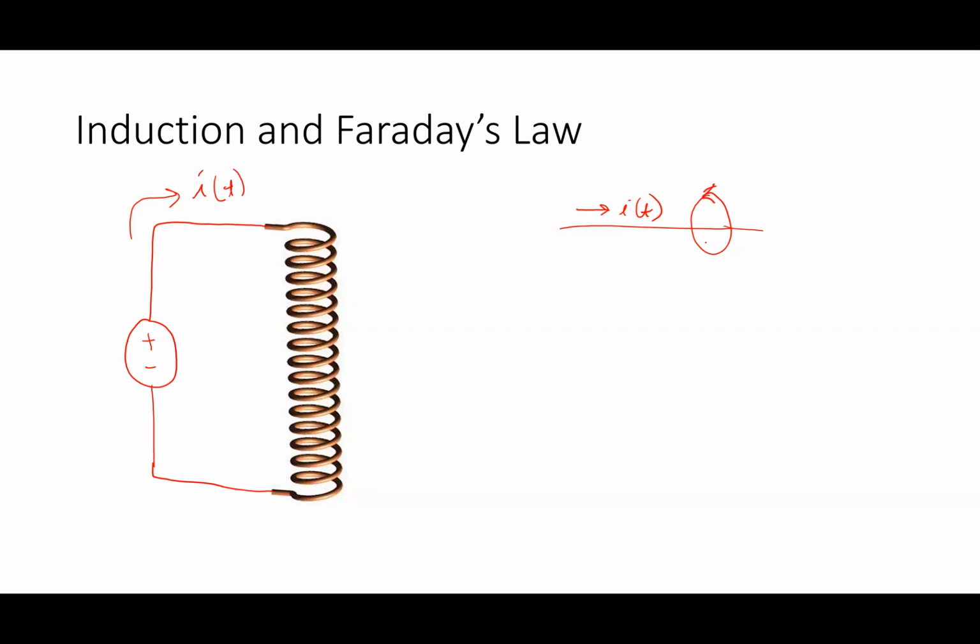So if I had a coil like this, and I had that I of T go in the direction that I have right there, where would the magnetic field be in this coil? Well, it would be wrapping around the wires, right? So in this case, where would it go? If the current's going into the top right there, where would all the field be from this thing? Inside the center of the coil. But wouldn't closed circles loop out? Yeah, it would go in the center of the coil and it would go around like this.